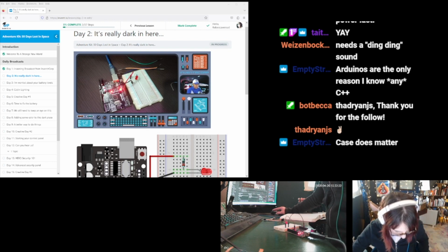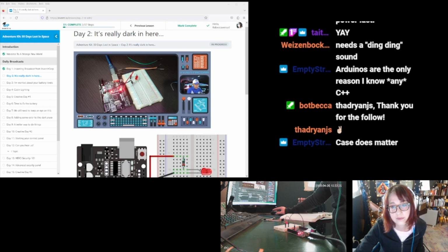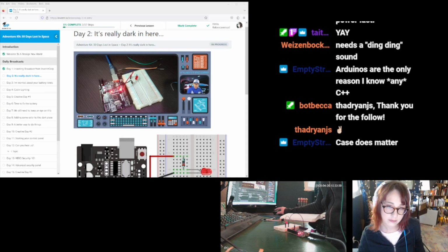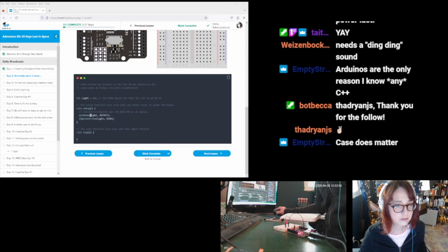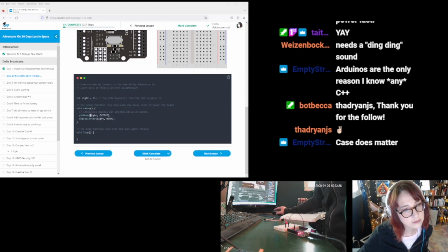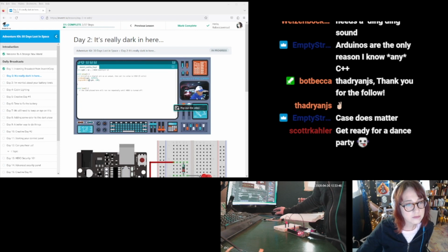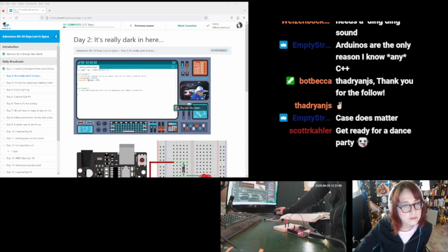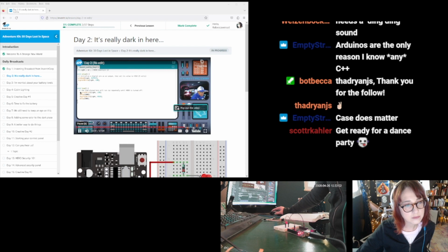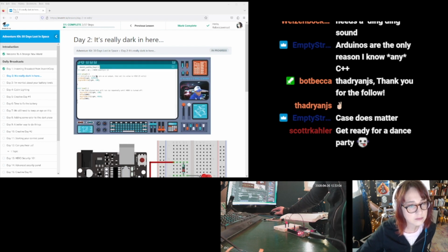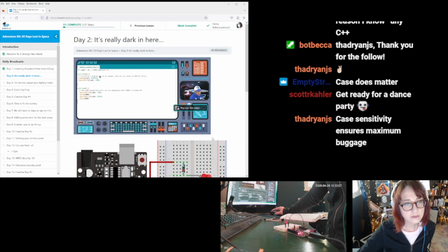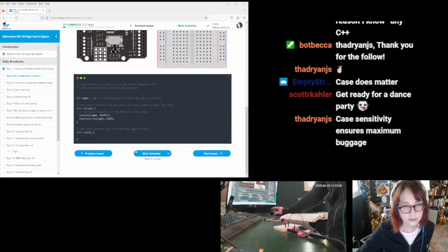Now, that's interesting, but we haven't even touched the loop function yet. And that is going to be very interesting for us because the loop function allows us to do things repeatedly. So let's see if we can do something a little more interesting by putting some statements into the loop function to be executed repeatedly. All right, so I'm going to use digital write again, but I'm also going to use a new function, and you'll see what that function is in just a moment when we take the code and paste it in. You'll notice, by the way, that we did have an appropriate comment in setup. We said that we are initializing the digital pin, in this case pin 12, and set its value to high.